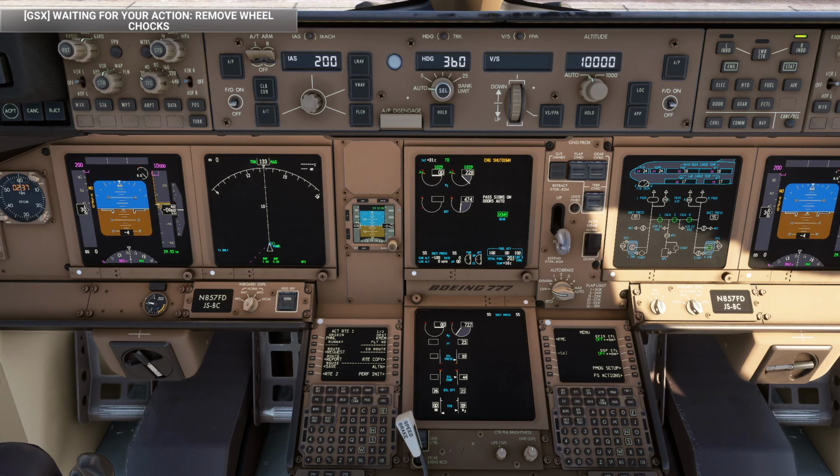So what I'm going to do is I'll speed up the sim rate again just so you can see that in 15 seconds as opposed to 60 seconds. And any second now, you see the duct pressure go up, and the packs should fire up here now, right? And there they go. So the packs are running, the air conditioning is going. The people back there, this is cargo, so if there are any animals back there, they're probably happy to have a little bit of airflow.